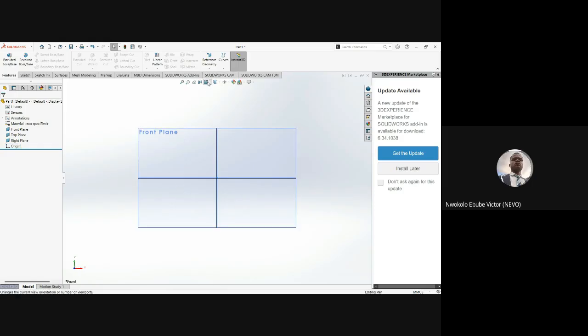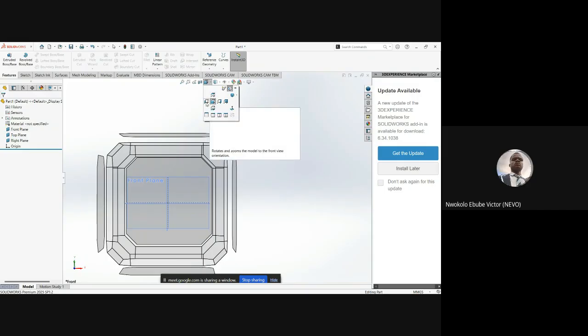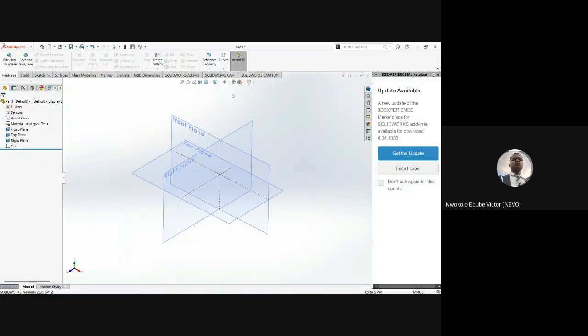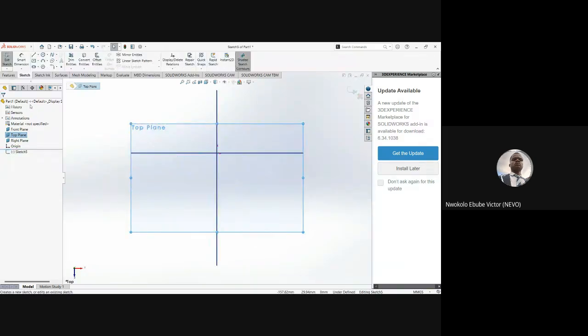So now moving on to the orientation. I explained to you guys the front view, the top view, and the other views, as I said, the custom views at the left and the bottom. Let's move to the isometric view, which I shared with you as an overview of the whole CAD itself. As I said, to create an object, you click on the plane, the top plane, then click on sketch. You draw, let's say, a circle. You can start anywhere, or you can start from the origin.